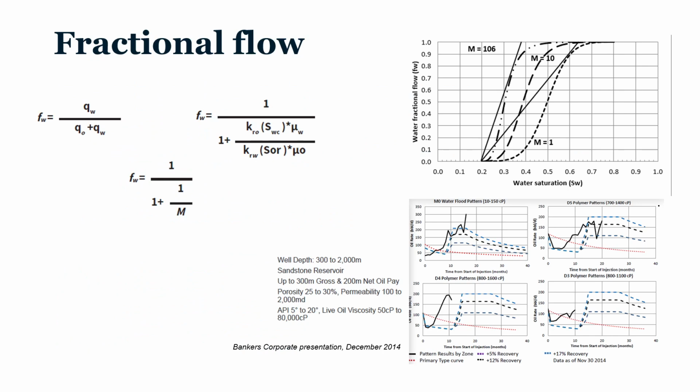So you can start with fractional flow. So fractional flow works very well. I mean, obviously. The thing is, some people and operators like Hilcorp have been using fractional flow to benchmark the recovery, and they have very good insights about what's happening. And fractional flow also tells that you should consider increasing the viscosity of the injected fluid if you want to improve the recovery. So basically, you should not do water flood alone, you should do viscous water flood from day one. That's what's coming from fractional flow.